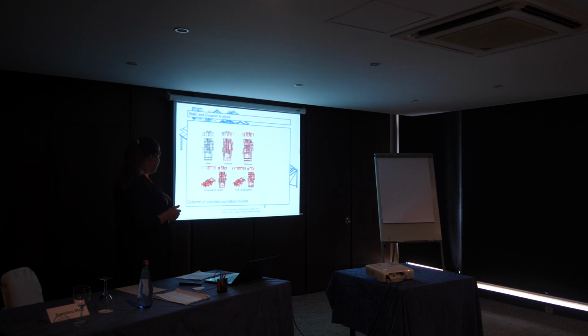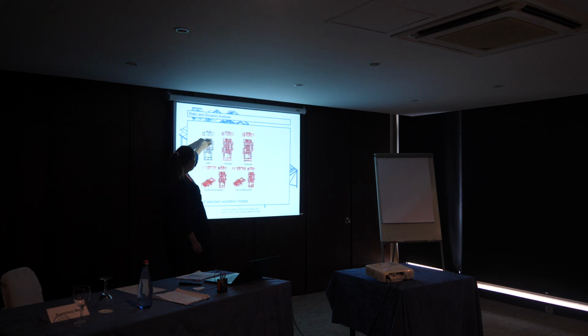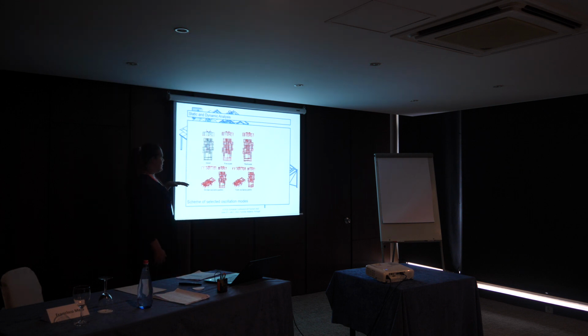Dynamic calculations were done, and we obtained the free frequencies of this structure. I don't think that I have that analysis in this presentation, but we obtained 20 free frequencies that are lower than 20 Hertz, and only 5 of them concerned some peripheral oscillations of those parts. That means that all low frequencies were in the zone of the robots. So a resonant behavior is expected.